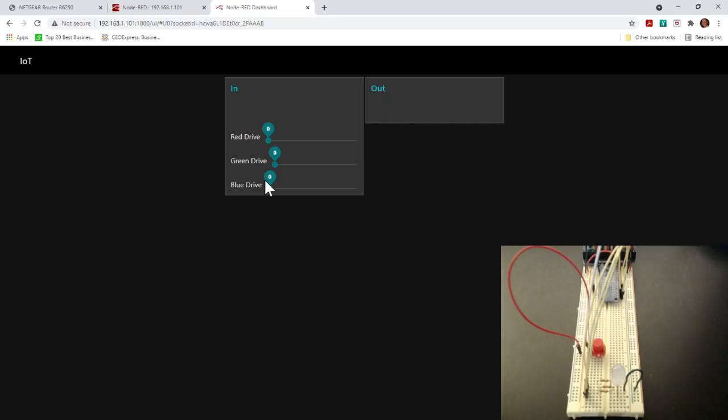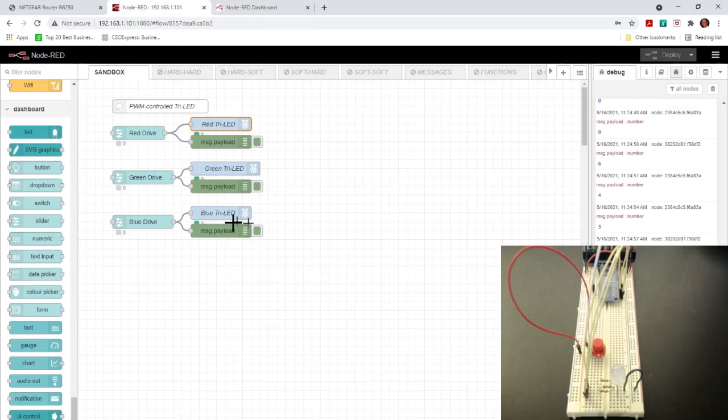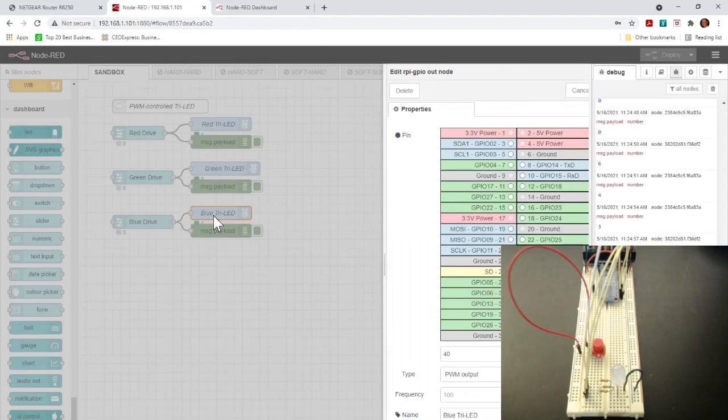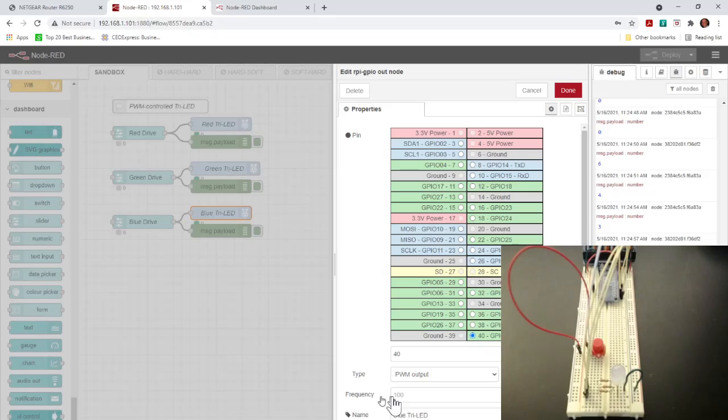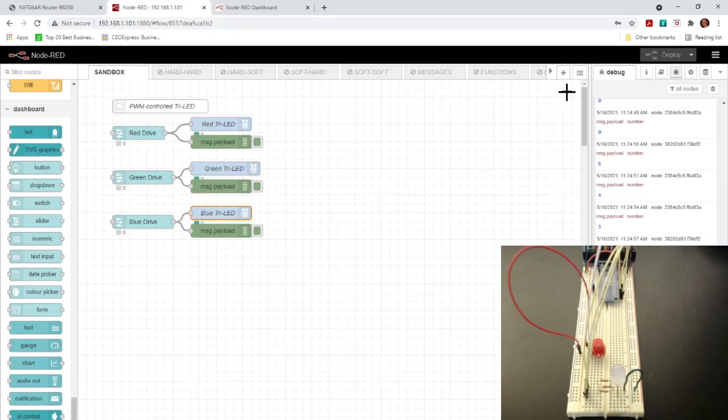So if you get to play with this, then you'll see that you have total control proportionately by using the pulse width modulation to change the proportion of on time versus off time of an alternating 1 and 0 output. And we can see what that output is based on a frequency of 100 hertz. In other words, it goes back and forth 100 times per second, and the input signal changes the amount of on time versus off time. So that's that experiment.